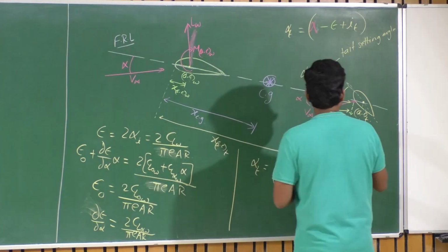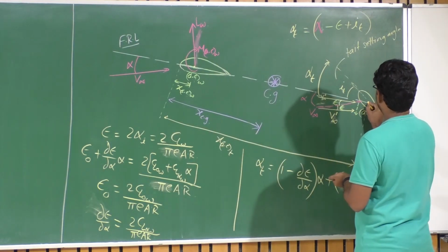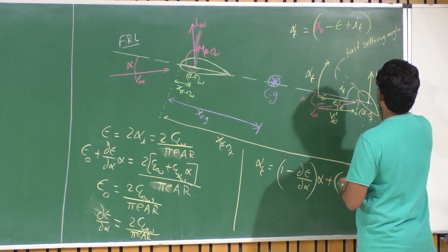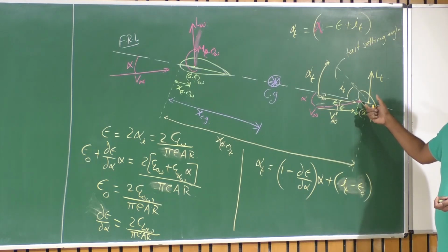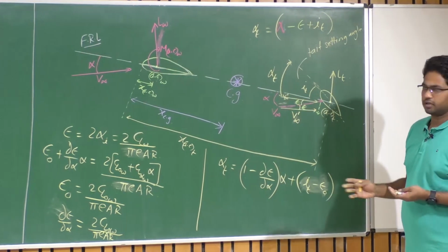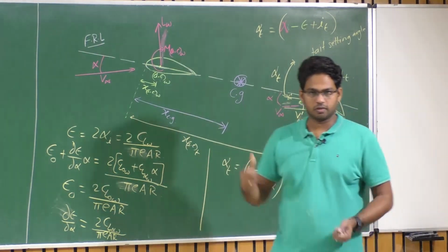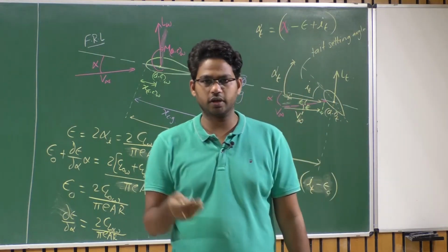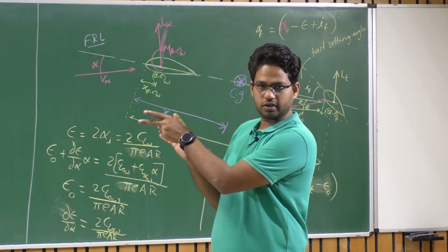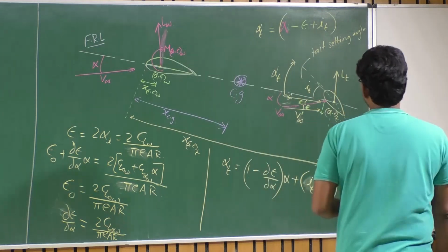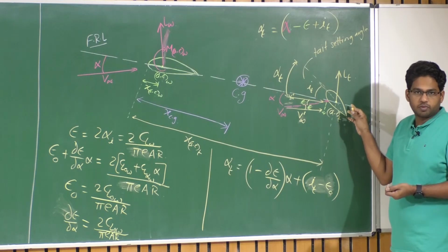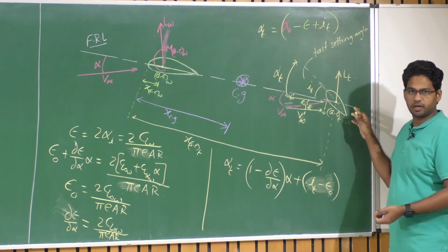So now we know the lift at the tail will be acting perpendicular to V infinity prime, which is L of t, right? There will be a little drag, but we are neglecting the drag. That horizontal component or the vertical offset of CG is not considered, right? And we proved that that is not affecting much. With that flat plate flight, we demonstrated that if that is small, it is insignificant for static stability contribution, isn't it? So I have L of t, but I don't have a moment here, isn't it?